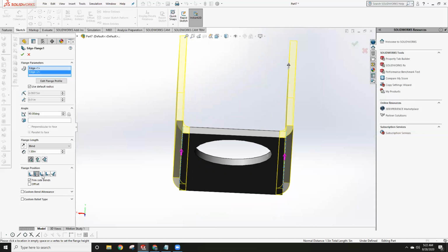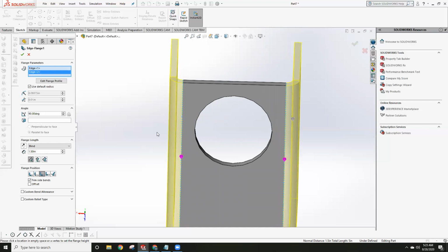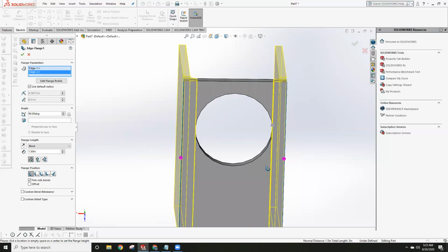If you want to do other things, you use bend out and bend from all these different ones. But what you would use bend outside for is if you've got something like a cut going up to the very edge, and then you want the bend to be outside of that, so then you don't have to deal with that. But that's also annoying to deal with. So what I recommend you do is use material inside, because it's much easier to account for, in my opinion.